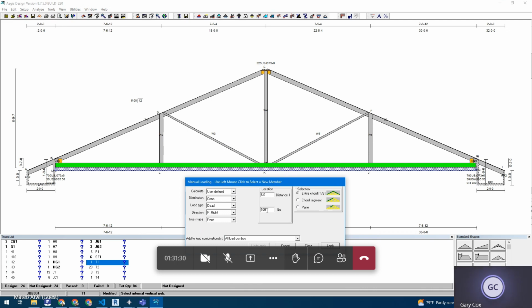It's attached across 3 trusses, and at 2 spots. So then you would take 50 pounds, divide by 6 points that it's going to be attached to, which will distribute the load. And then that's what you would enter as the weight.